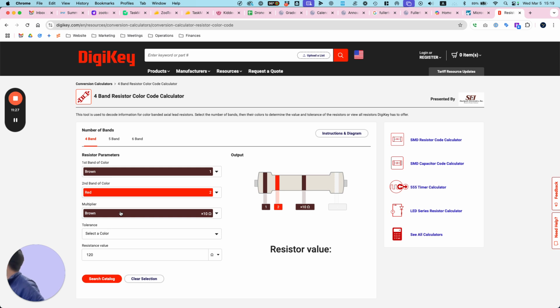So what matters the most, really, because we have some variations, right? All these are theoretical values. In reality, the resistance might need to be a little lower or a little higher, and we can play with the voltage ultimately too. But what matters the most is actually this multiplier. What if we used the next number, which is brown, orange? That's 130 ohms. If you do the calculations again, it's not really going to change much, okay? So this will be fine.